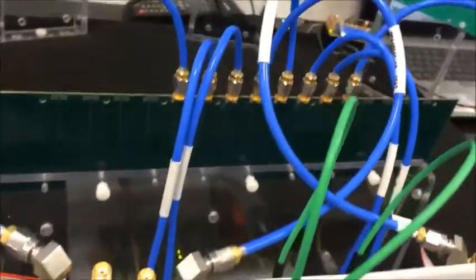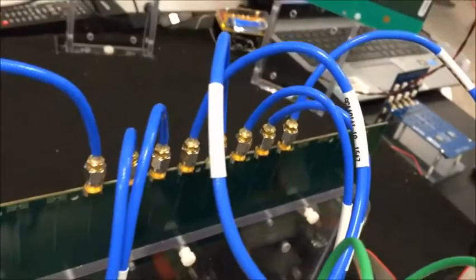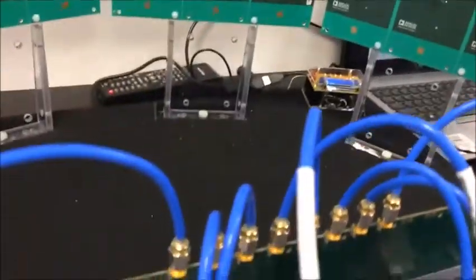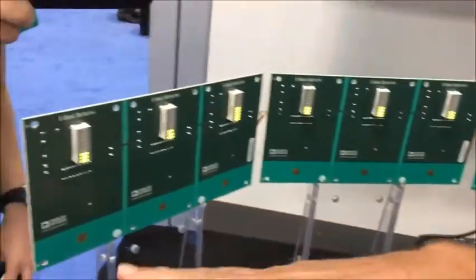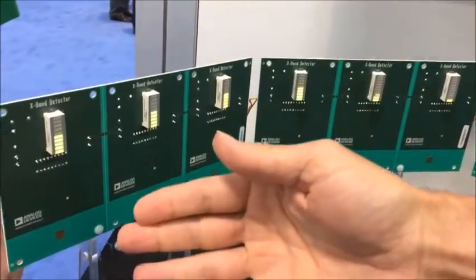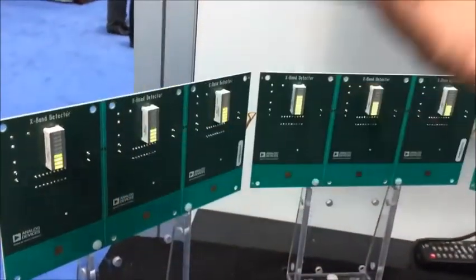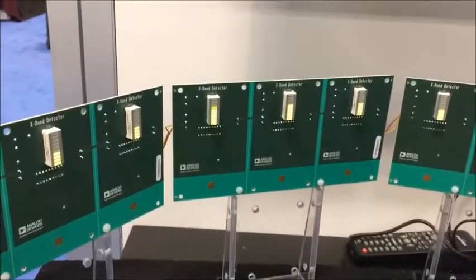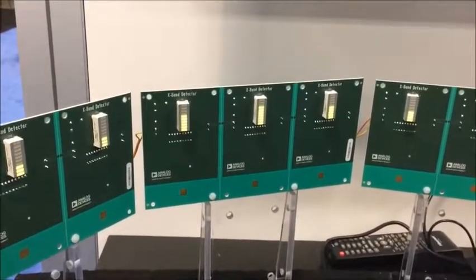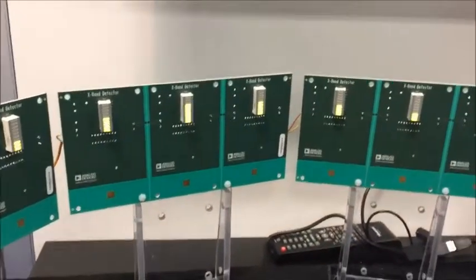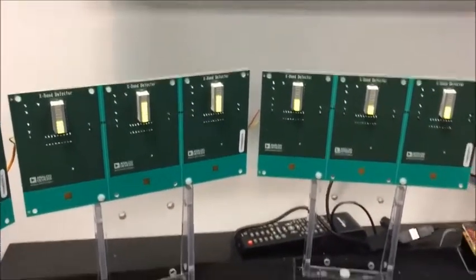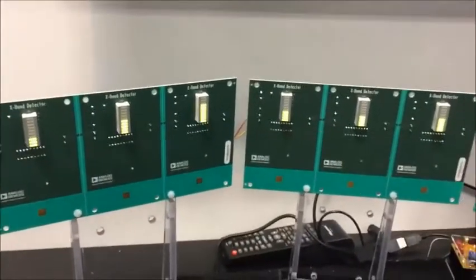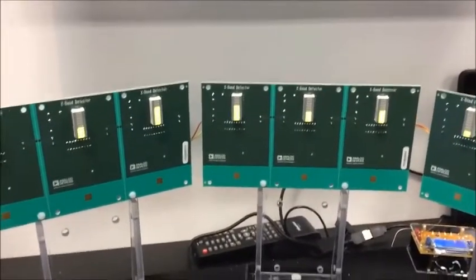And the demo has 2 evaluation boards. We have a common input to 2 4-to-1 analog beamformers, to 8 outputs to a line array antenna, and then we're electronically steering the beam, and our display is a series of antennas to power detectors to a display, so the display is an indicator of RF energy in that direction, and we're steering the beam across angularly. Okay, from left to right. Yes. Okay. And that's being done by controlling the phase shifts in our beamforming ICs.